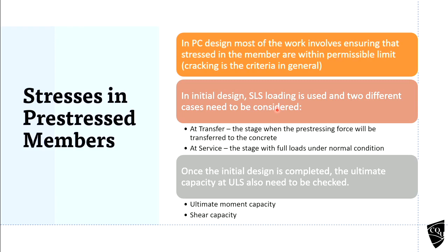We should use the load combination as per SLS. You know the load combinations for ultimate and serviceability are different. So we should use the serviceability limit state load combination for the initial design.